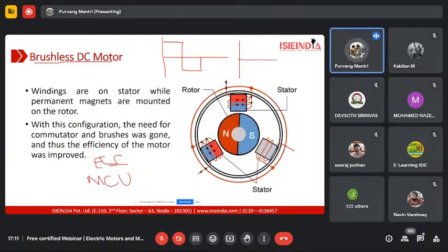A proper AC current is sinusoidal, but DC current is straight. It is a direct current, and the voltage does not change with respect to time. But for a brushless DC motor, we need to switch the current so that the windings can switch polarities, and that's why we use a motor control unit to switch the current direction. Now, these were the two basic types of DC motor. Brushless DC motors have been used in many vehicles by now, and they are highly desirable.